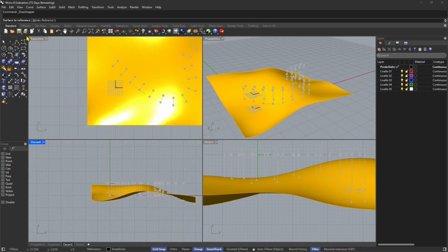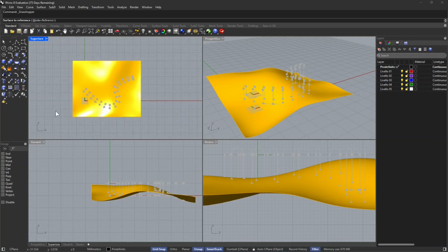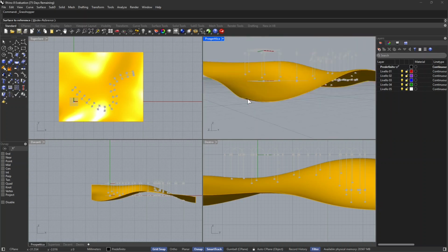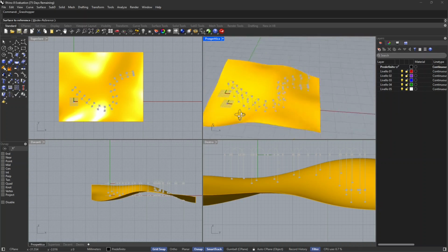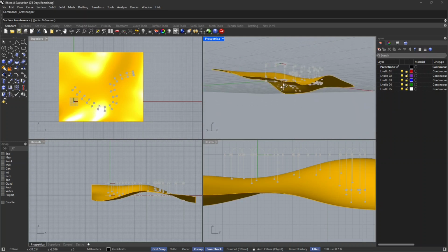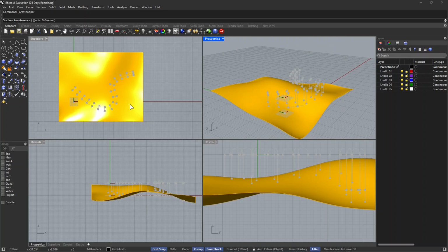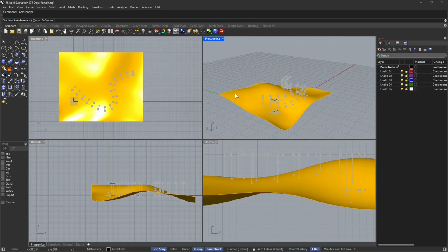Now if I do that right now, if I right click and set, you can see there are no references here in the scene. There is only one surface, which is the one already used, but this is also internalized, meaning that it's no longer in Rhino, but embedded into Grasshopper, so we can bake it to put it back into Rhino. But let me show you here.